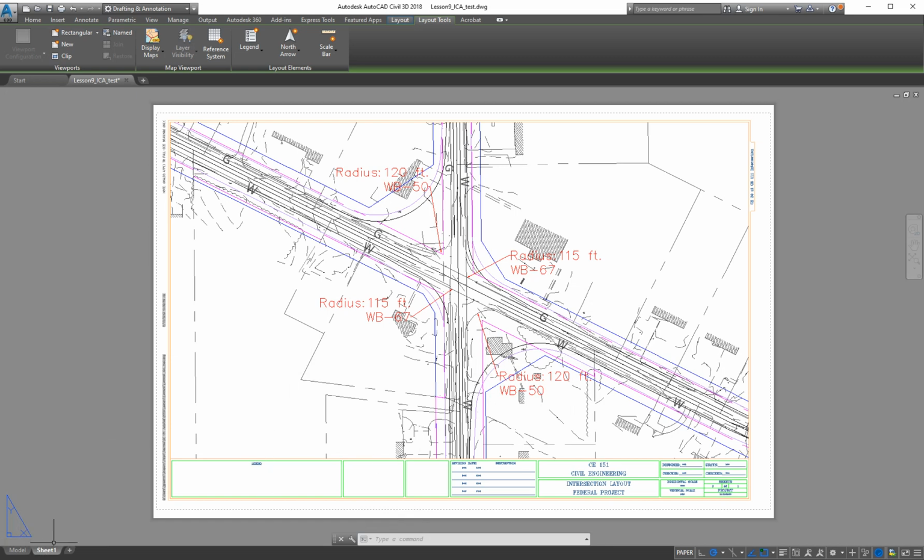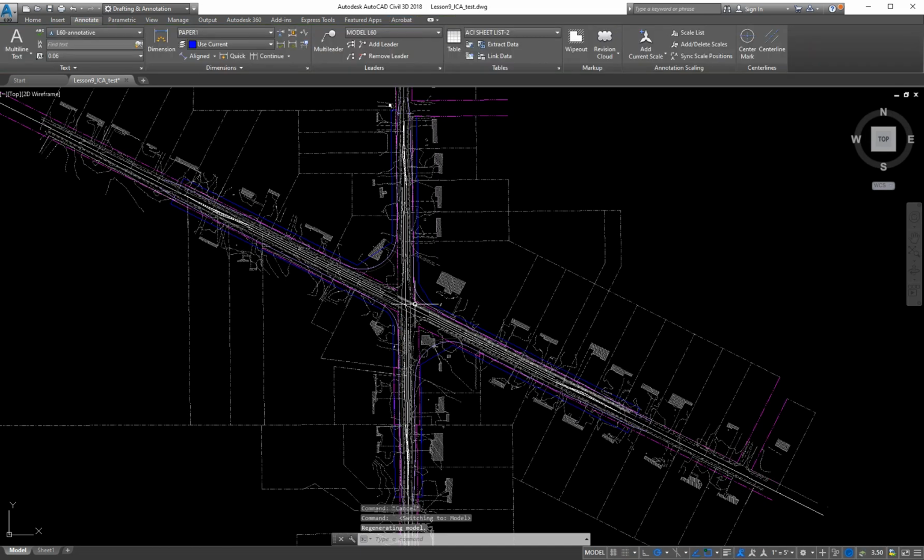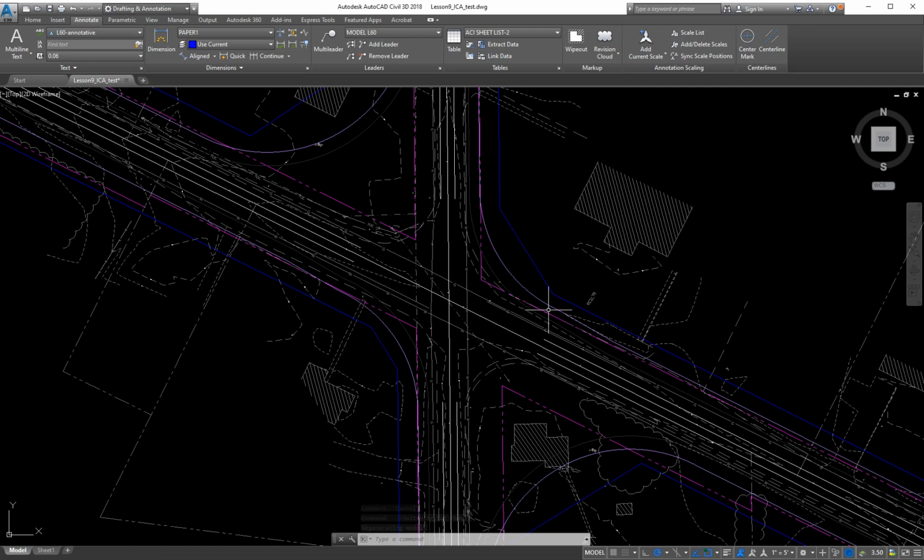Before we did maybe some basic stuff in paper space in a real simple plot, but most of it was still in model. Right? In a production environment, in a real job, everything is going to be in paper space. Your title block, all that stuff is in paper space, because the reason they invented all this was to make our lives easier as we're plotting. Right? And we can reuse this model view multiple times in different sheets, and all we have in here is the base line work and design stuff, right?